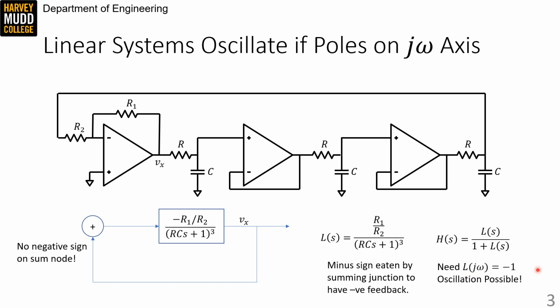It's worth noting that this analysis hinges on the phase of the loop gain, while the magnitude is something that we feel like we can just correct as an afterthought. That's an insight that should guide the analysis of most oscillators. The phase of the loop gain is hard to change, so it determines whether a circuit will oscillate, while the magnitude of the loop gain is relatively easy to tune, so it often isn't a deciding factor in whether you can get something to oscillate.